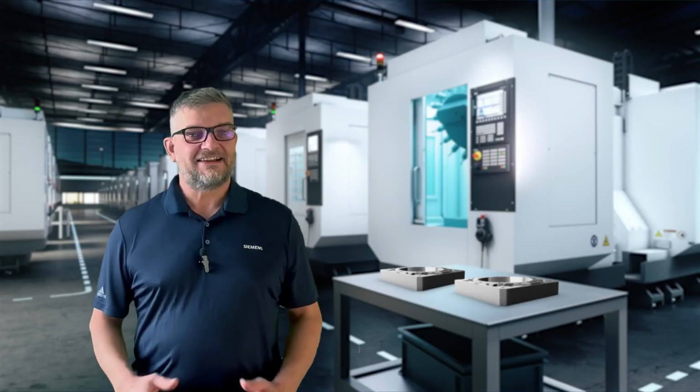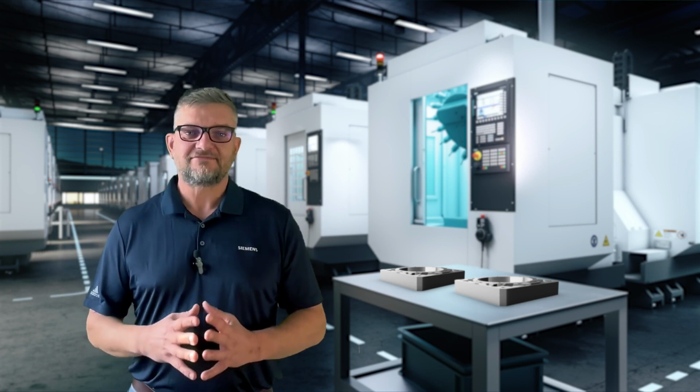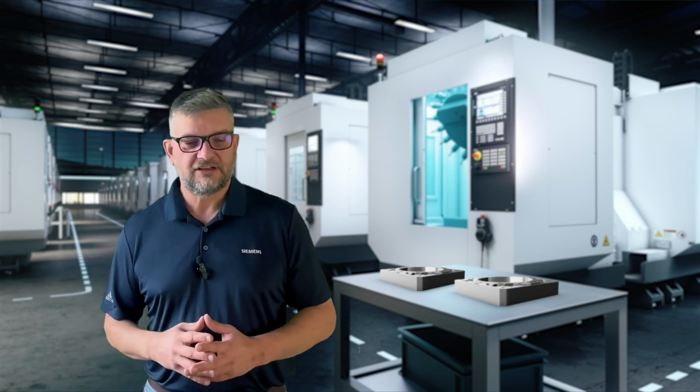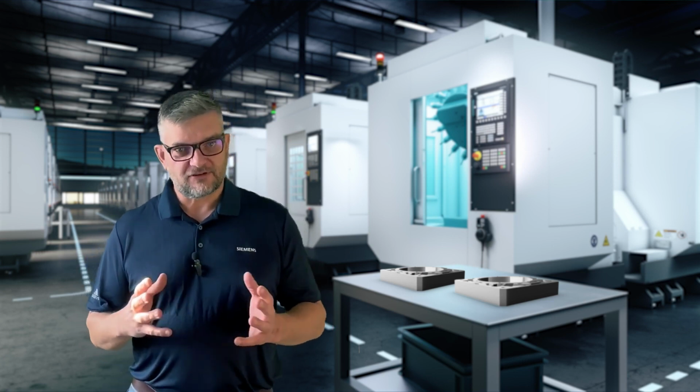Now that we've seen Ashish showcase the new quick roughing operation, an important addition to our 3-axis milling capabilities, it's time to shift our focus to the exciting world of 5-axis machining. Yet another new operation is called Wall Finish Barrel Swarf. As the name infers, it's a 5-axis finishing operation to be used with different types of barrel tools. And it's very good for cutting deep pockets or deep planar walls.